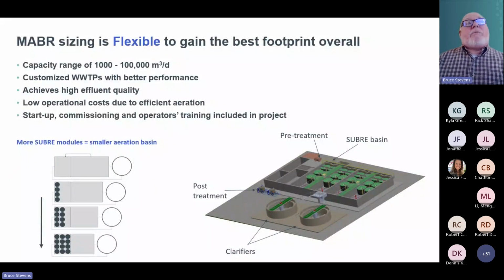We allow a maximum of, I think it's 50 parts per million of FOG to pass through. But then we have a fine screen, which is below 2 millimeters, so it's a 1.5 millimeter or lower screen, which takes out any real large particulate TSS and rejects it to waste and digestion.